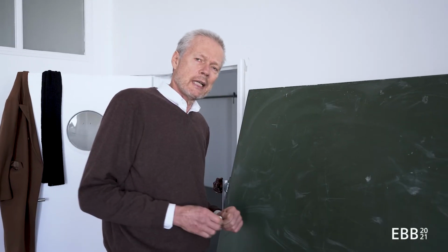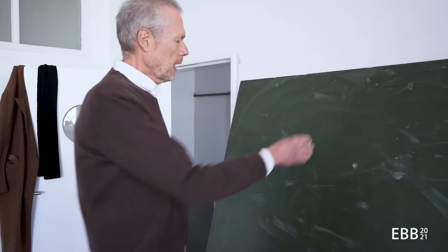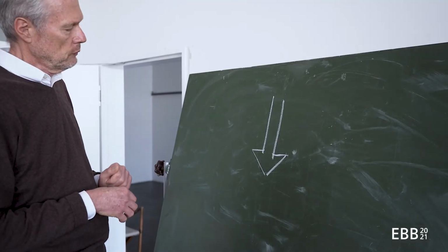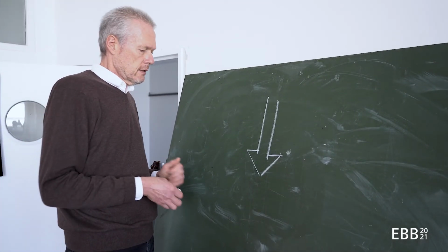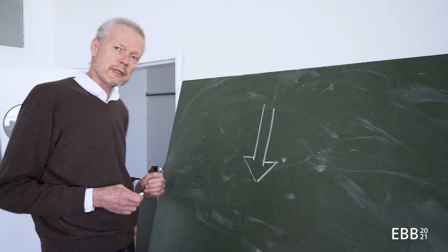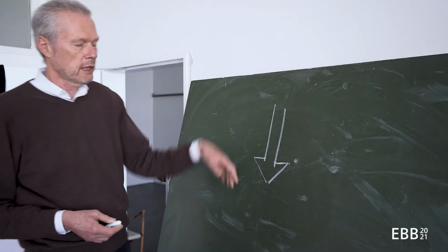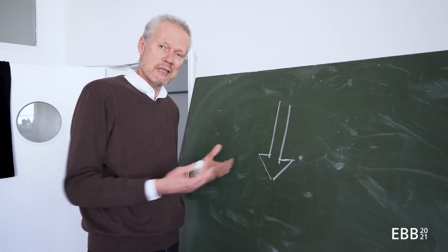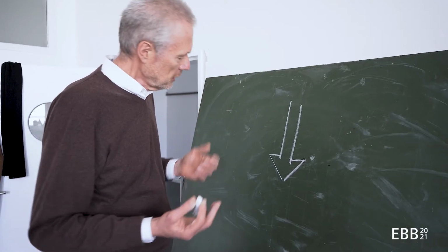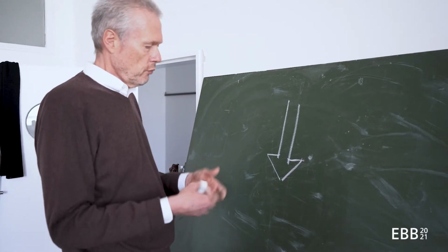So when it comes to the ground, I will have to transmit the load to the ground, and I will have to spread it on a wider surface to guarantee that the maximum admissible tension of the soil is not overreached, so that the soil will not break.